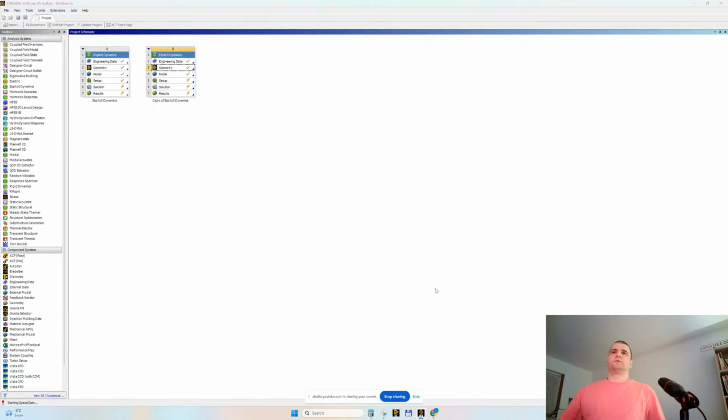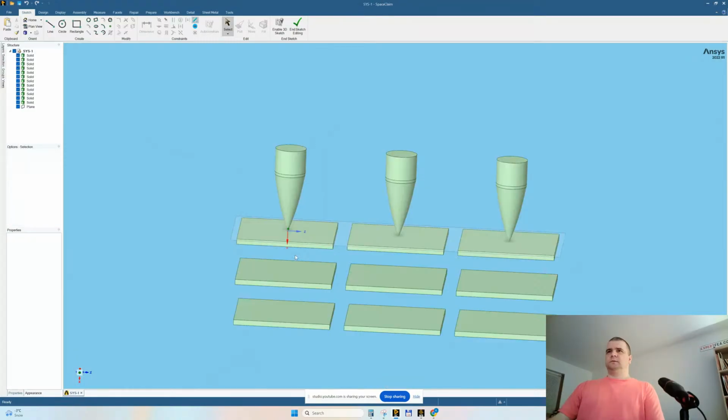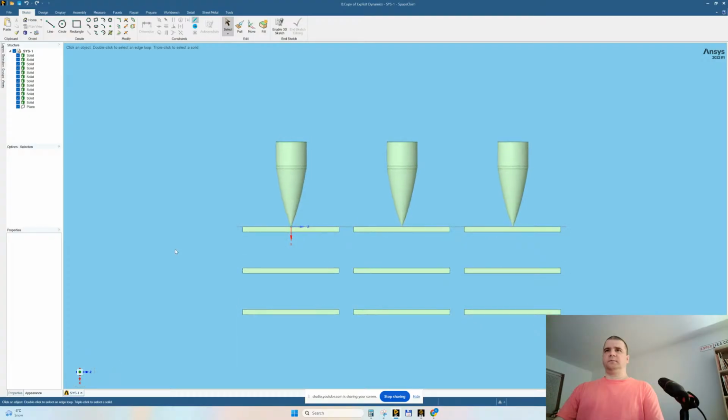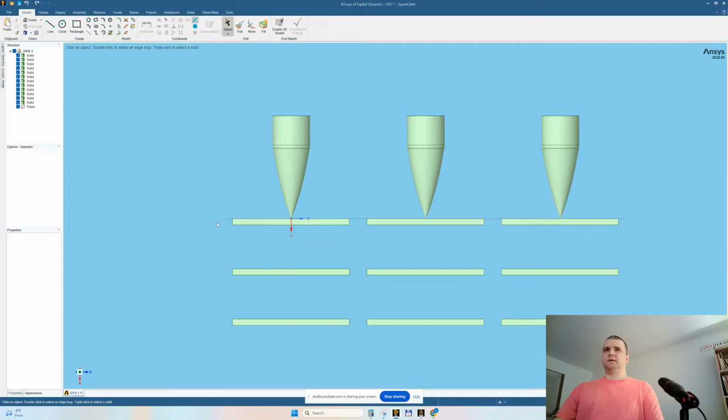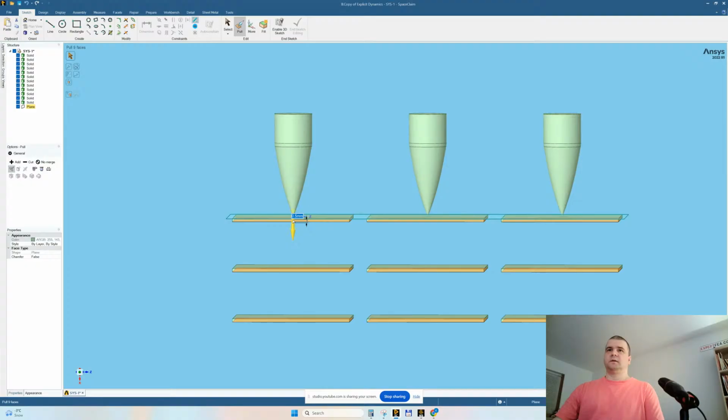You know, we want to captivate the audience, and we will do something spectacular that appeals to everyone and anyone. So I said that the plates should be thinner. Let me select them with Control pressed. You see them? And we're going to write a value 0.5 with minus in front of it. 0.5. All right.